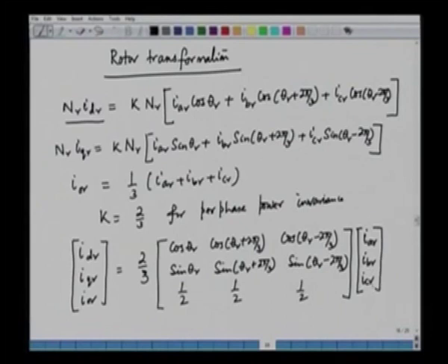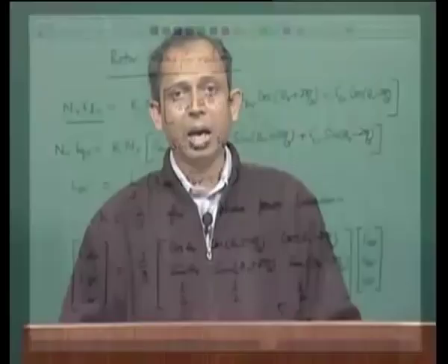So, we have the rotor currents, and this matrix here is called the rotor transformation matrix, that is CR. What we have done here is find the transformation matrix for the stator and the transformation matrix for the rotor, and having found that, we can transform the equations in ABC variables into the equations in DQ variables. So, this transformation IABCR can be transformed into IDQOR.